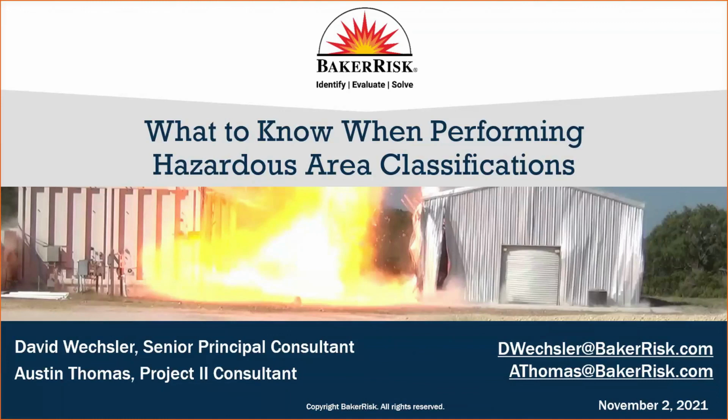If you have a condition where the hazardous area is going into the roadway, that's a condition that you may want to think about and look at. An example of that type of condition might include areas where we have screened in or fenced in areas where you have control points for pipeline areas. These are sometimes on leased land where we have a fence around it, and we don't know what's going on beyond the fence line, but we generally stop the hazardous area classification at the fence line because in some cases we assume that's the limit of what we want to deal with.